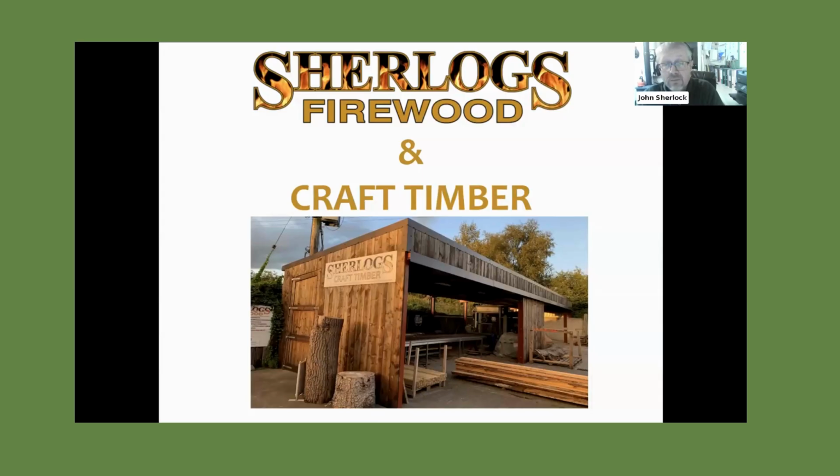And the first question I ask them is, how long of a straight stem have you got on that? And the rule for me, Ian, because it's my own sawmill and it's handy to saw, is you need at least 2 meters before it's worthwhile sawing it. But I'd be saying 2.5, 3 meters of straight timber, really with no kinks, bends, twists, or, as you say, forks. Now, out of some timber you will get some really nice looking timber suitable for slabs, for tables. But really, for somebody to get something usable, that's what we want.